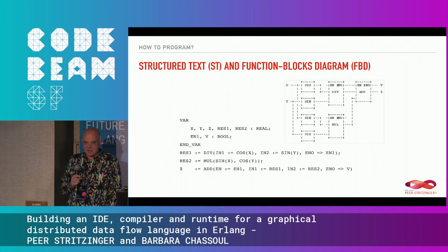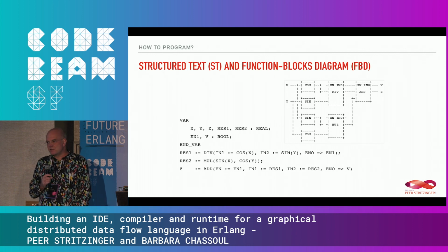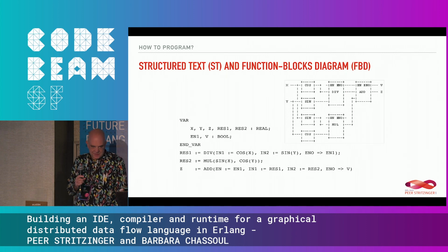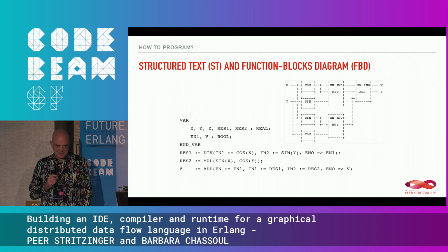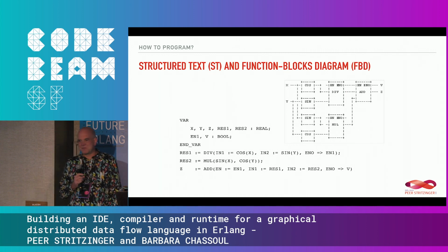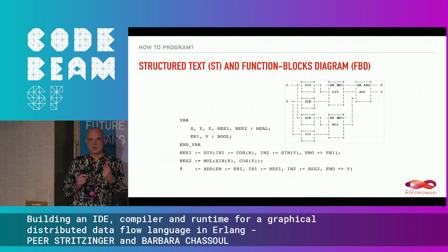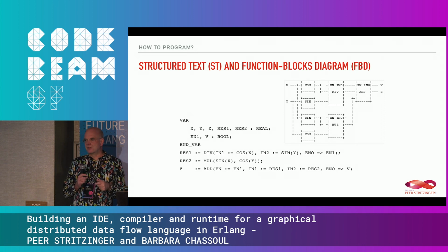Later on, they made a thing called structured text, which is a Pascal-like language, because that was a language that was widely used when it was actually designed. So you have this colon-equals thing for assignment, and it's case insensitive. It all smells like Pascal, the whole syntax. But it has specialized types for PLCs, like data types for time deltas, or data types for wall clock time, and specialized fixed point data, and all kinds of things.